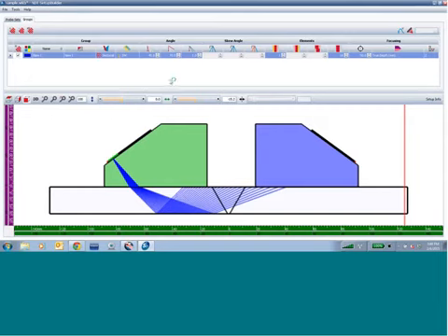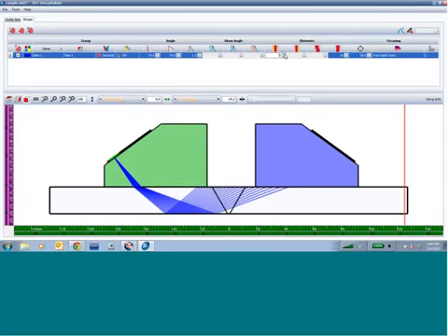So what I'll do is, this is a 30-degree bevel, so I know that I need angles from 50 to 70 degrees. So I'm using a sectorial scan. Here's the 50, here's 70. So what I can start with is just ensuring that I've got these beams properly placed.